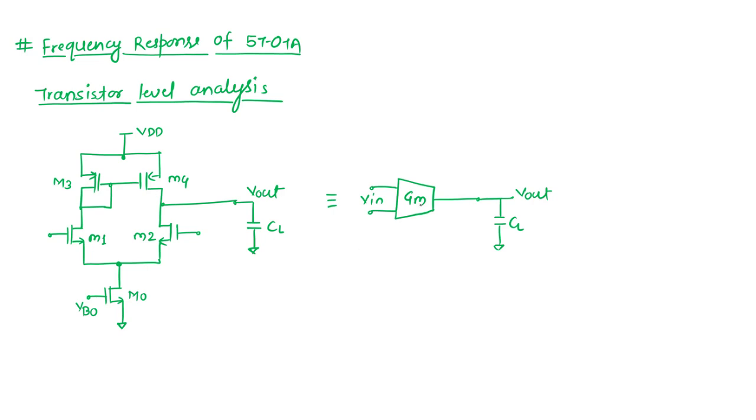So I have drawn two structures here. One is simple five transistors and one capacitor load, and the other structure is where this five transistor structure itself is replaced by a GM cell, which we are discussing thoroughly till now. So ideally, if I'm considering both the cases, let's say the output impedance of this GM cell is infinite, then what we have seen,